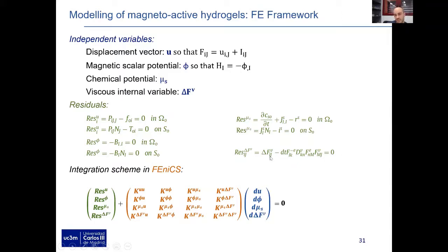So basically, it's determining how these evolve consistently with this viscous contribution to the rate of deformation tensor. By imposing the residual, we can define any given viscous flow rule, and then we can put it into Phoenix. We can test many different combinations of constitutive equations, constitutive fields for every single bit, and we can easily get a first approach. Of course, this is not efficient from a computational point of view, but we can test many others, and once we have our optimal solution, go for defining these matrices manually.